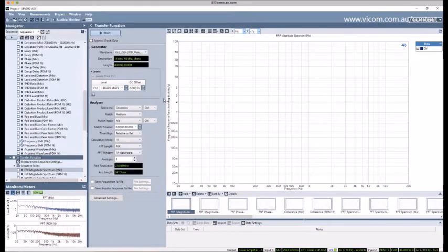Now, the next little bit that I do have to admit is that one thing that is confusing is that the signal generators in AP software are calibrated according to the peak level of a sine wave. If you're generating a different kind of signal, in this case a speech signal out of an APX, and it has a different crest factor, you really have to add that crest factor to the signal level in order to get what you might expect.